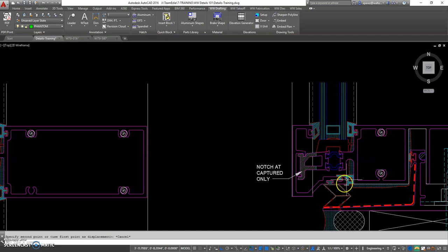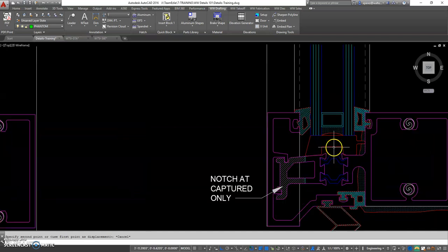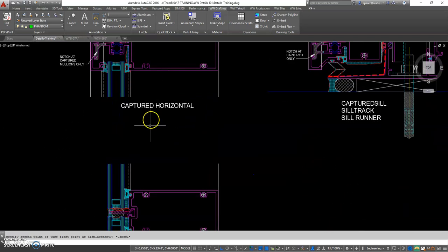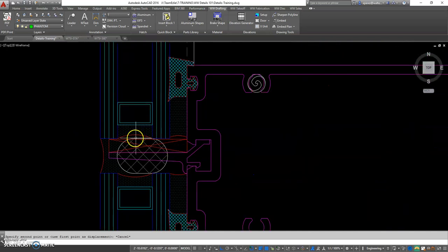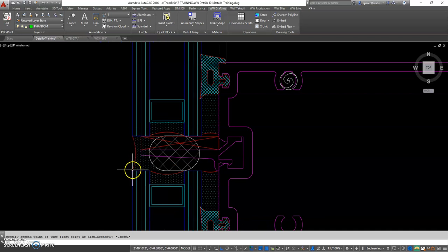Horizontally, we have a couple new pieces here. This block, which is what the glass sits on, is called a setting block. Those are only 6 inches or 4 inches long, and they are only at the quarter points of a unit. Each piece of glass needs 2 setting blocks. On our Inviso, it's just a nice rectangle represented here. This is what we call a setting chair, which helps support it. Again, these only occur at quarter points. It's not continuous pieces. And here we don't use a gasket between the glass, we actually use sealant.